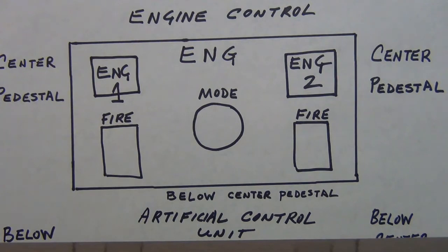Now the switches, when those switches are on, I mentioned it's about how it opens up the low pressure control valve if it's in an automatic mode. So it is controlling those fuel valves. And it's going to start that engine starting process, right? Which start has to do with what? We have another valve that I mentioned earlier, your start valve.